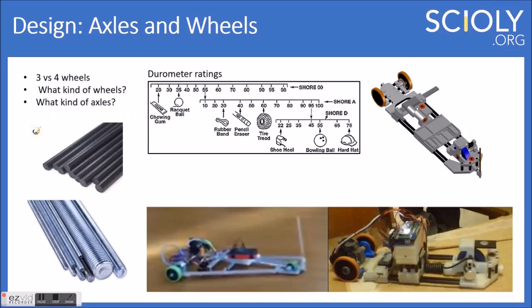But once your device starts getting heavier, if you all of a sudden brake suddenly with, say, the 30A wheels, you're going to start really degrading them very fast, and they're going to lose their quality, and you're going to see these little rubber pieces falling off of them. So you might want to switch to a less soft wheel, which would be the 40A or the 50A. So it kind of depends on the mass, I would say.